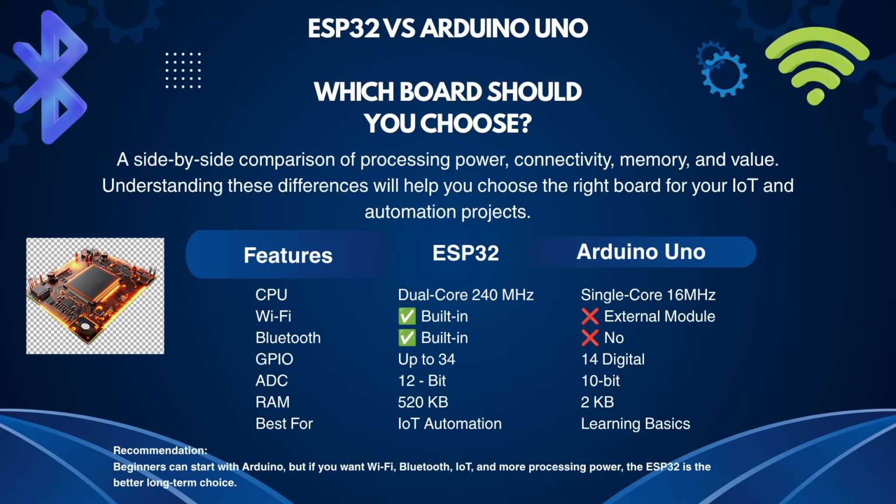The Arduino Uno provides 14 digital input and output pins, which are sufficient for many basic projects, but offer fewer expansion options. For analog input, the ESP32 includes a 12-bit analog-to-digital converter, providing higher measurement resolution than the Arduino Uno's 10-bit ADC. It also has 520 kilobytes of RAM, compared to just 2 kilobytes on the Arduino Uno, making it much better suited for multitasking and memory-intensive applications.